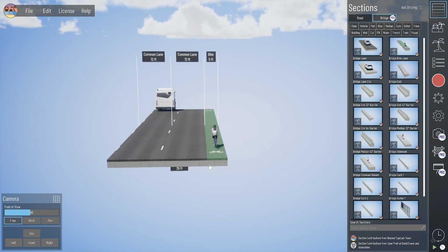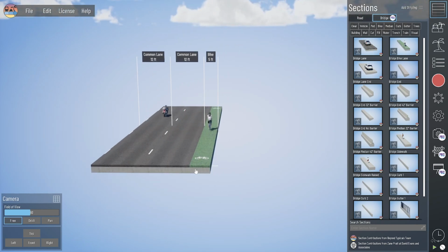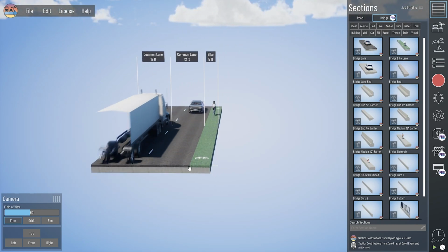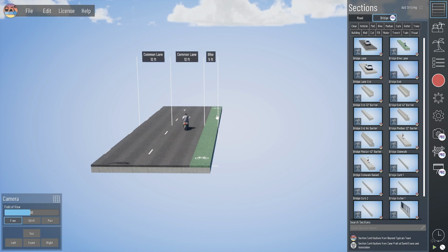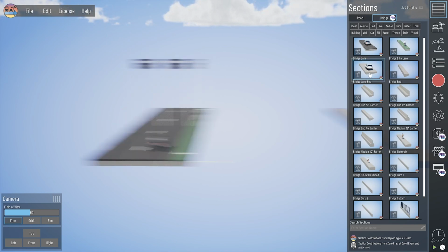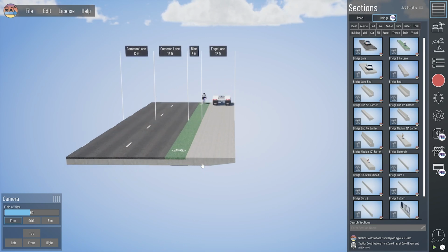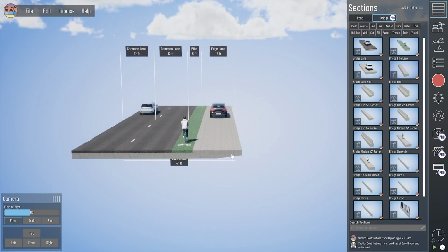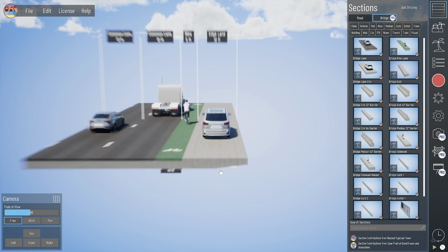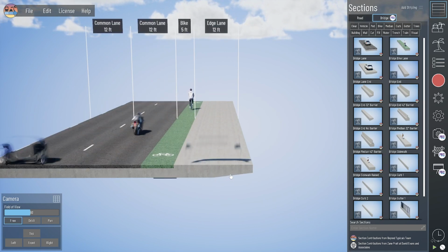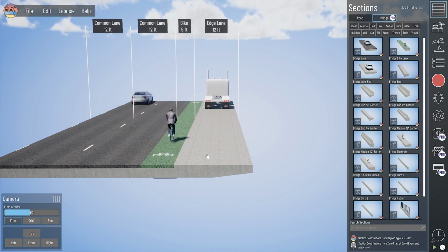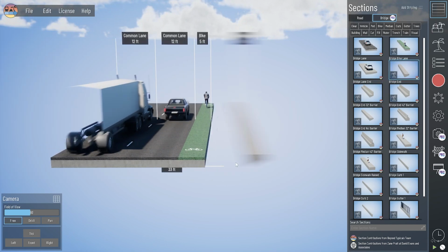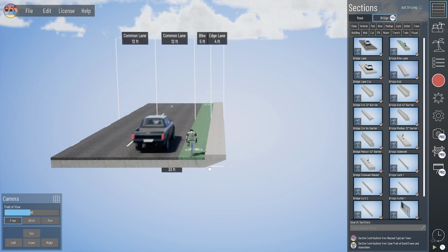We've got a bridge bike lane, which is similar to the bridge lane, where we've got that concrete base, but by default has a green textured pavement, and our cyclists are the moving traffic on that lane. We've also got a bridge lane end, which by default has a concrete surface and has traffic moving down it, but you'll notice the bottom of our concrete base tapers up toward the middle of that section.